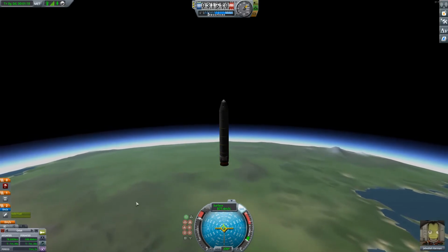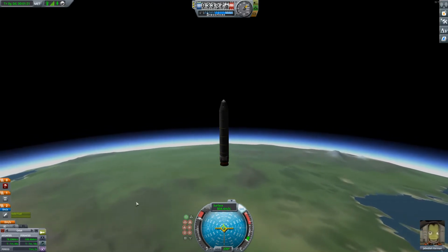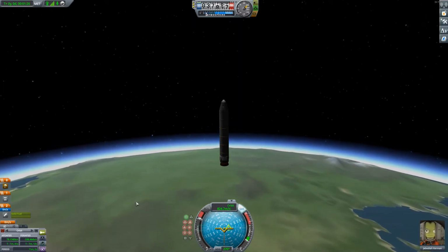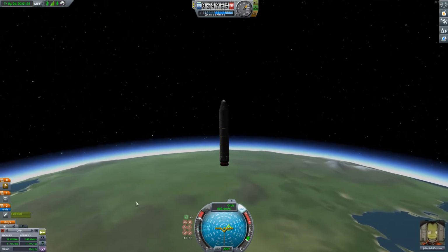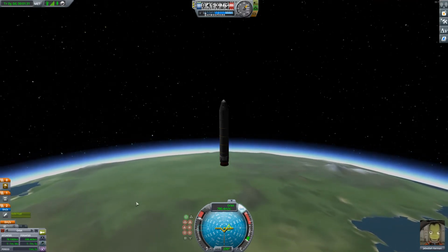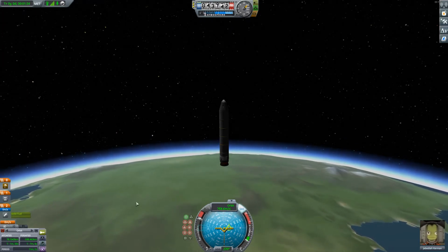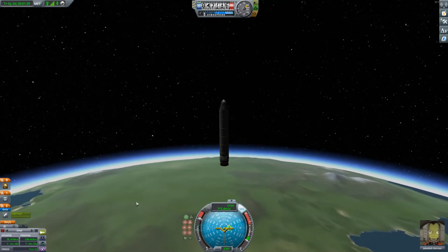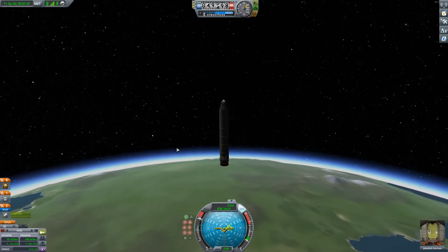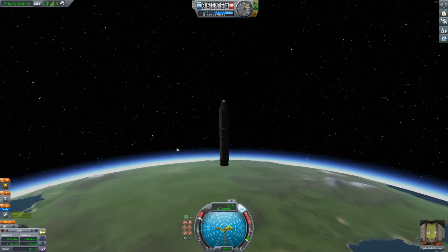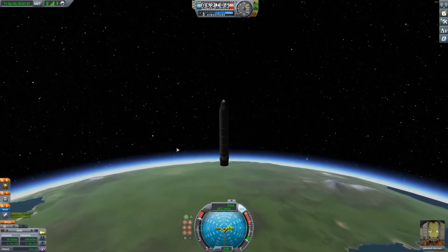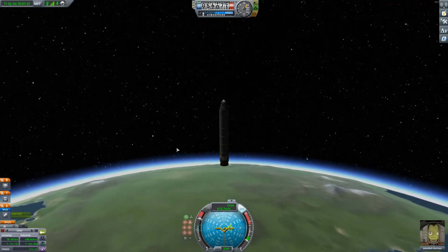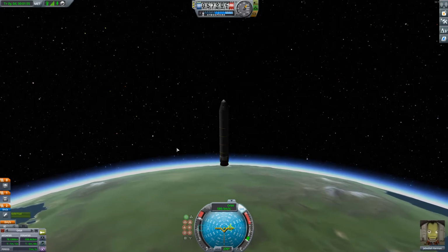But there are many pros and cons to using a solid rocket motor. One of them is that you can store the propellant on that rocket for a very, very long time without much propellant degradation. And they always launch reliably because of that. For this reason, they're actually used a lot in military applications like missiles, when you want a rocket to always go off. And there are not a lot of moving components associated with it. There's fuel on the inside and a nozzle. It gets a little bit more complicated when you add thrust vectoring into things, but for the most part, it's a very simplistic design in comparison to the complexity of a liquid-fueled engine.